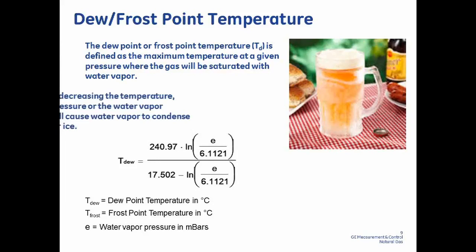If you increase the pressure, you will also increase the dew point. You have the effect of concentrating the water into less space. So that's important to remember, because very often we see comparisons of various dew point instruments. And if you're comparing dew point instruments, you either have to install them at the same pressure, or you have to make adjustments or calculations if the two instruments are at two different pressures.